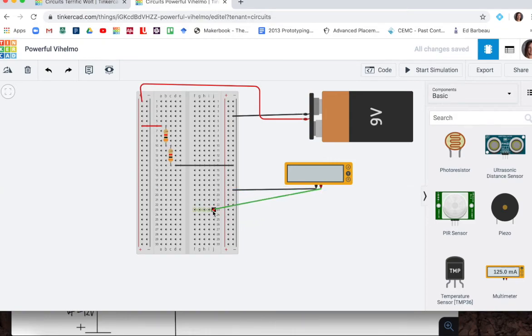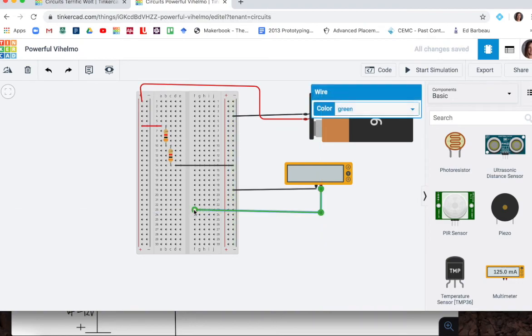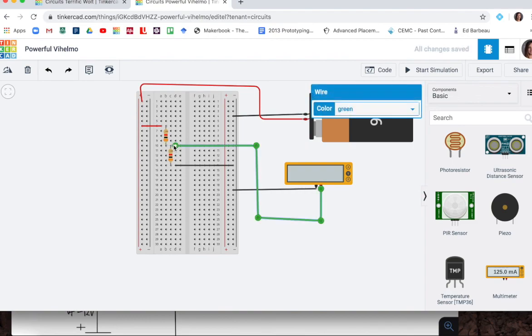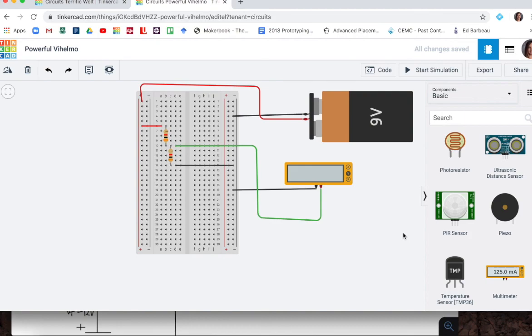And you'll know that in our circuit, the thing we were interested in was the value right here. So from the bottom of R1 to the top of R2. And let's leave that green because it's not power. We're just taking a measurement. So now when I start my simulation, I should see the output voltage. So I'm going to get you guys to do that.